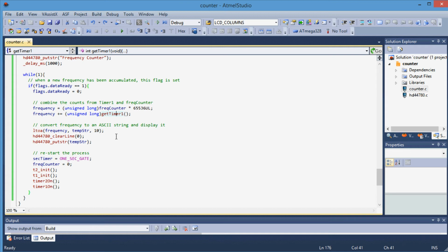In other types of microcontrollers, the Microchip PIC controller, for example, you can do the same thing here, but they do not have the requirement of the external clocking pin to an internal counter being synchronized with the main oscillator. The pin is directly connected to the counter, and you can clock that timer counter register as fast as the register can handle it. And I believe the spec in the Microchip PIC parts is something approaching 50 megahertz.